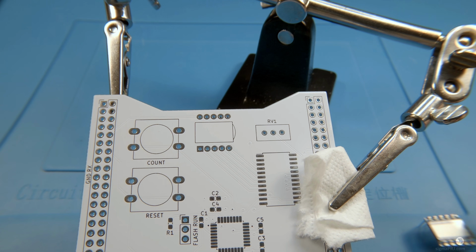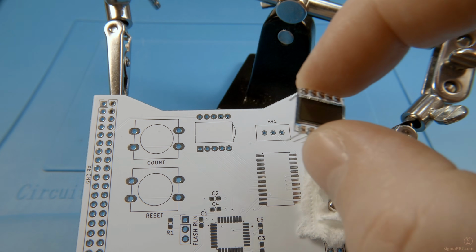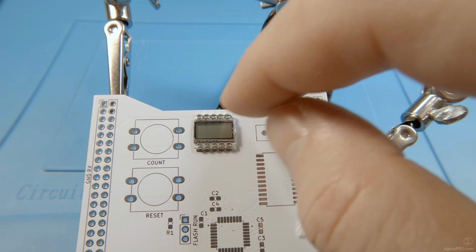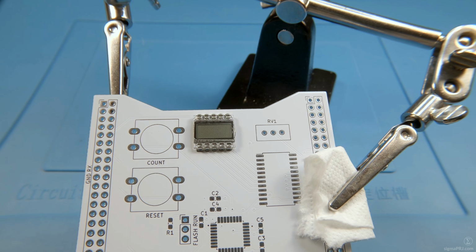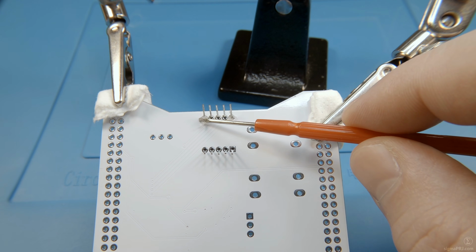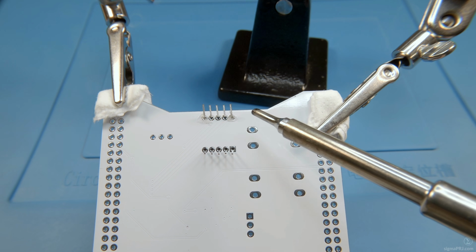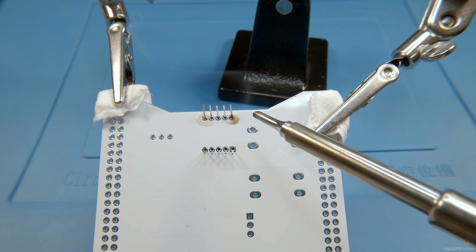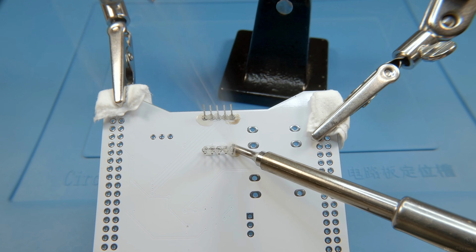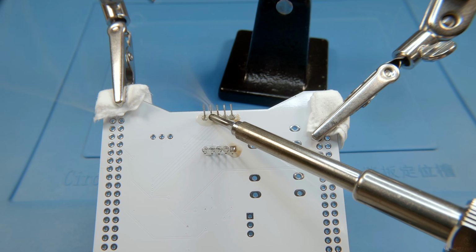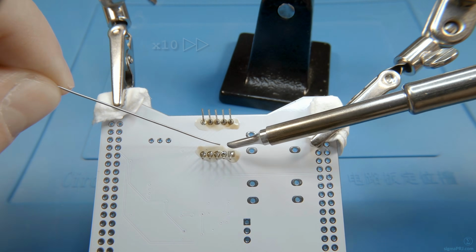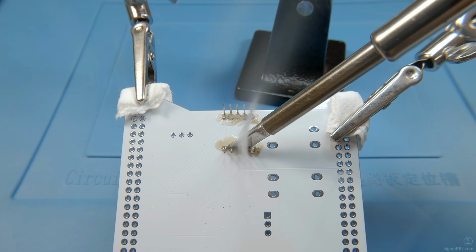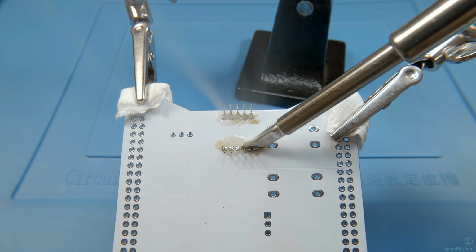board. Now let's start with LCD component soldering. Let me place it here. We also have to take proper positioning into account. This is a through-hole component with 2 mm pitch size. This way we'll be following standard through-hole soldering procedure. Nothing special here. Now we can use key-type soldering tip just to remove any excess solder around the pins.